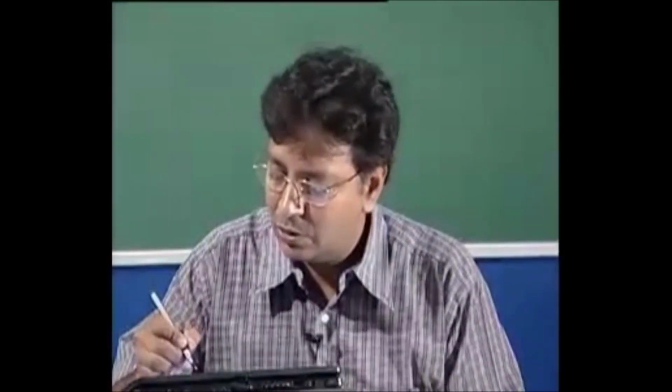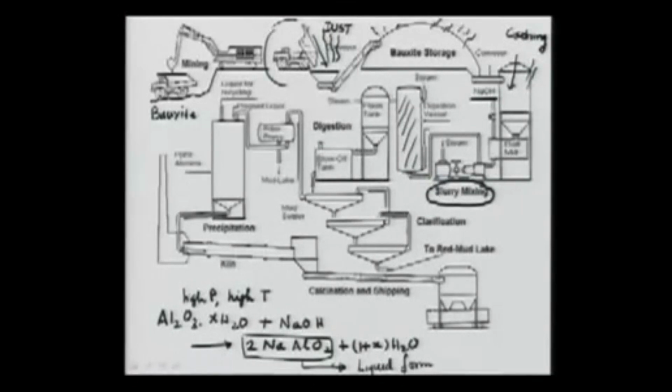So the next step is what you see is the flash tank, okay, that you pass through the steam, and then from the flash tank you come to the blow off tank. Essentially it's a kind of surge tank where you can transfer the things and then bring it to the various settlers, if I can call this, or clarification. You probably will recall the clarifiers that we use. Essentially what we are trying to do is separate out the suspended solid components, which are the impurities.